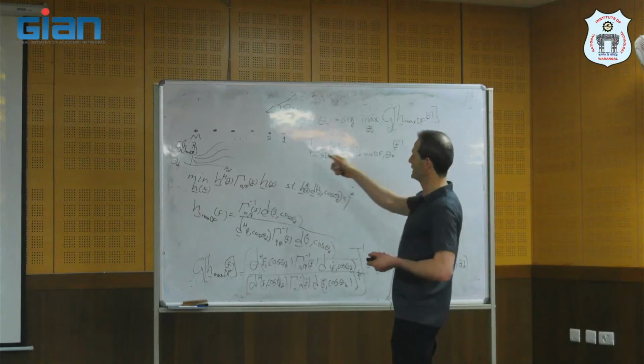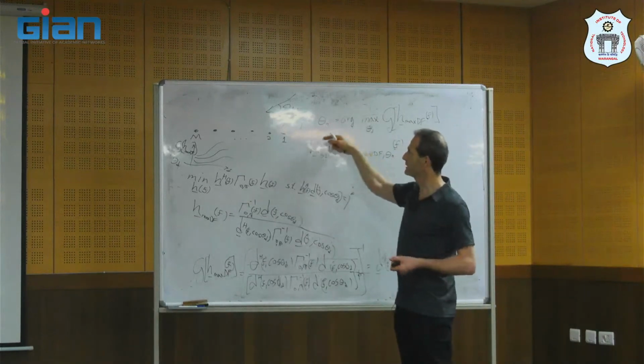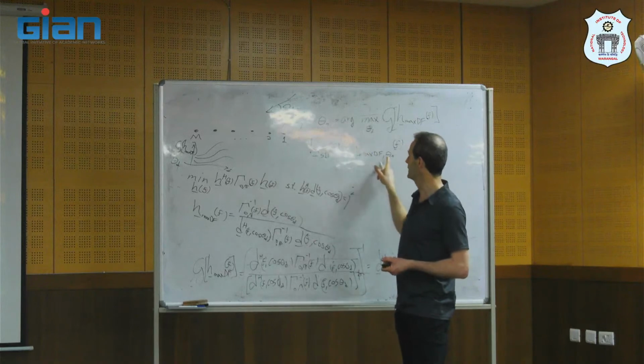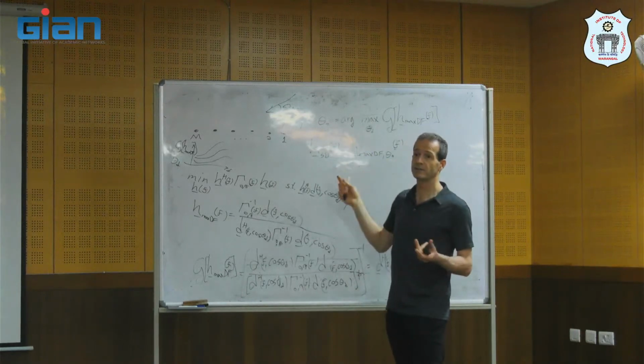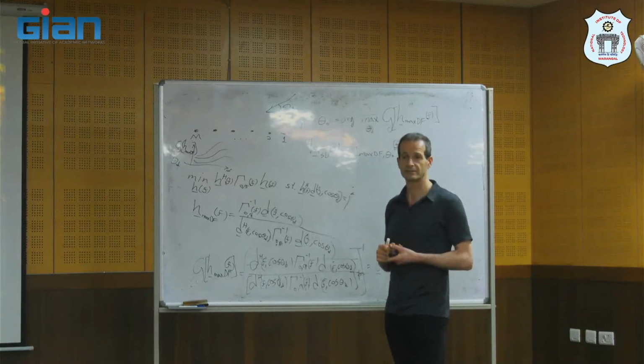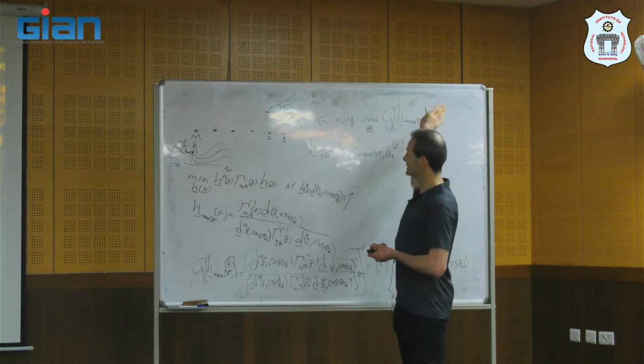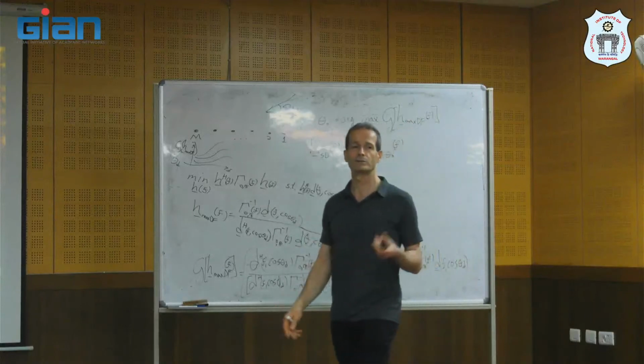And actually, for this kind of array, the maximum directivity factor is obtained for theta d equals 0, and it doesn't depend on the frequency, which is also nice. So it maximizes the directivity factor for all frequencies.